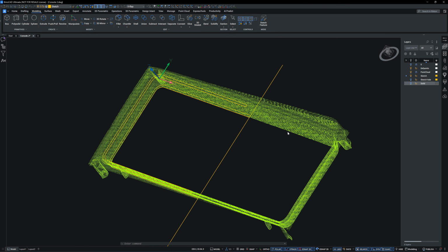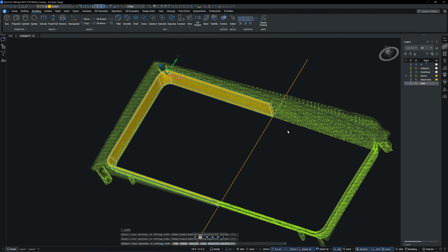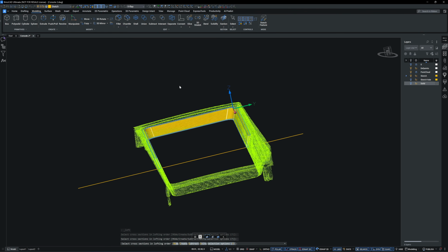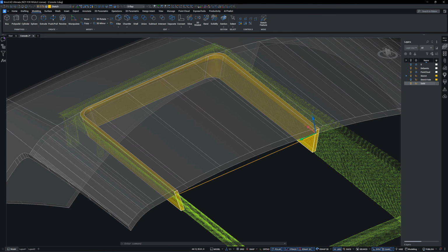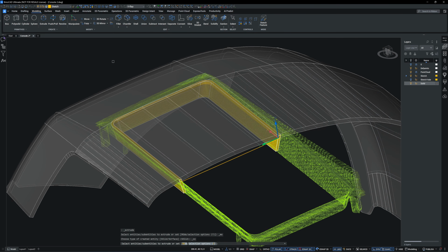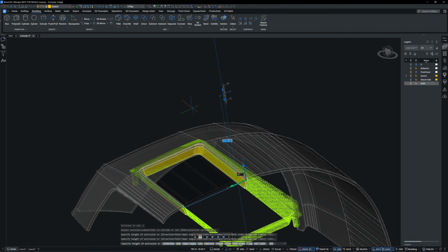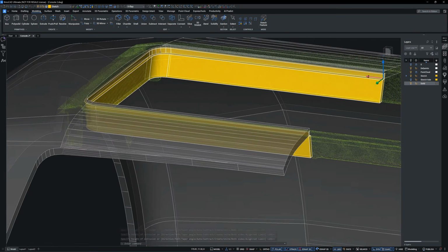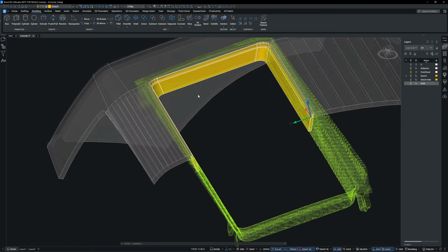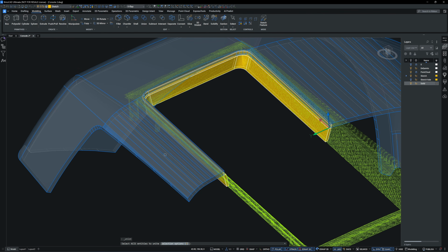It includes a support wall extruding inside, and the walls are tapered. So before trimming, I will first create the support wall using a solid loft. On the edge of the support wall, I offset the cross section to create the cutting profile, then use it to extrude cut the bezel. Now I have a frame with a small step just like the original part. I then union the support wall with the bezel.